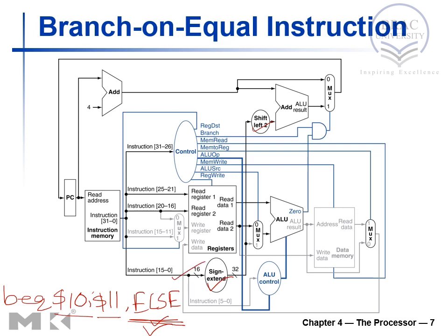So this link will carry the 16-bit value. It goes to the sign extension hardware, you generate a 32-bit value, and that is left shifted by 2. So this link will carry the branch offset value, which is 32-bit, sign extended and left shifted by 2. Now this link would carry PC plus 4.